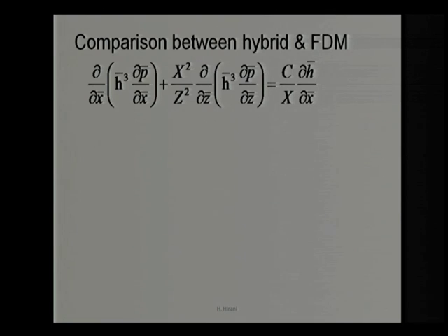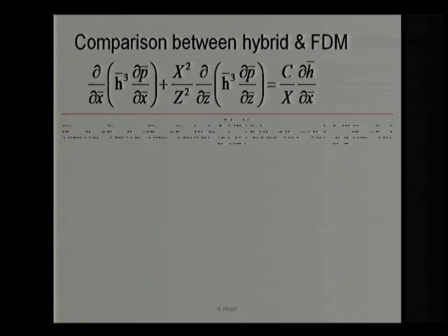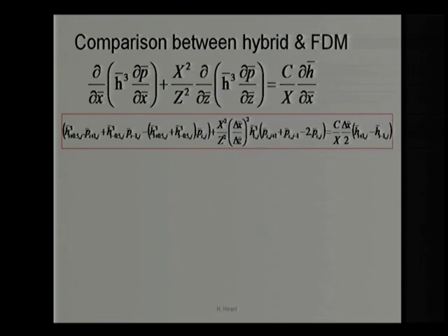But we need to provide some boundary conditions: what the pressure will be at the exit, and the pressure at the entrance, which are generally known to us. Many times we know the supply pressure, the pressure at which the liquid is supplied to the interface. Those things are known to us, right. So, when we try to incorporate those values to find out A, B, C, D in terms of geometry, we need to substitute all the expressions we got in the previous slide: the expression for the first term, the second term, and the third term.